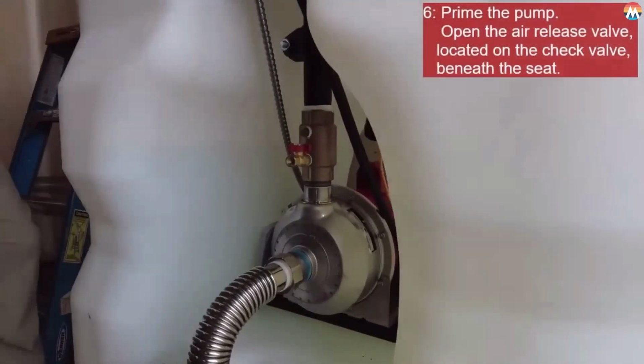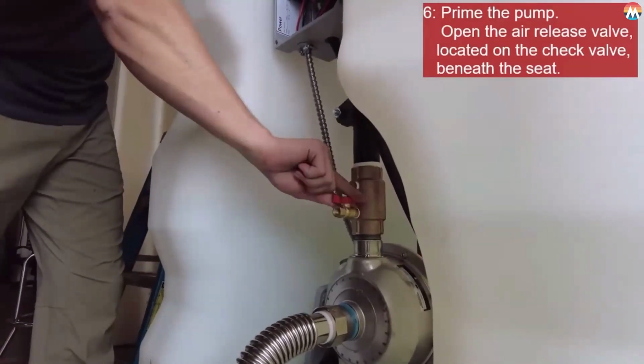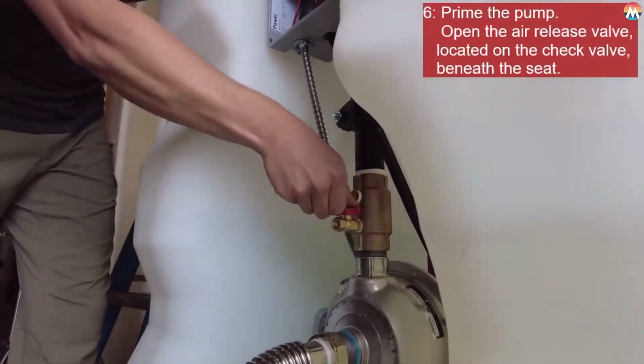Next, we're going to open the air release valve that's located below the seat of the check valve. As the water fills the volute of the pump, it pushes the air out. As soon as you get water out of the air release, the pump is primed.